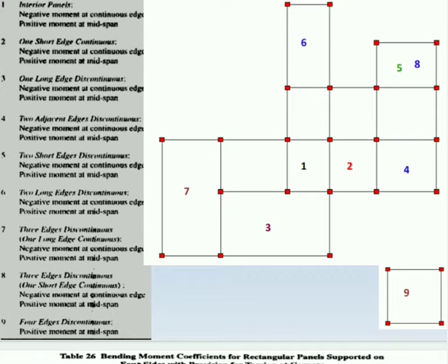So always remember, while solving examples based on the restrained slab, if any edge condition is not given, you have to assume that it is condition number 9, that is all four edges are discontinuous, as shown in the figure or box below, where all four edges of the 9th slab don't have any continuity on any side. So if in the example no edge conditions are mentioned, directly go to condition number 9 for selecting alpha x and alpha y. Whereas if the conditions are mentioned, you have to select the proper condition from 1st to 8th.